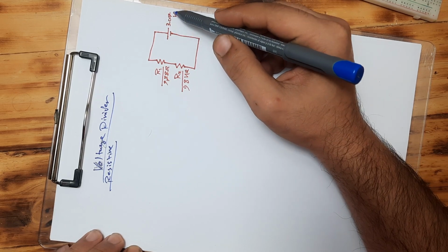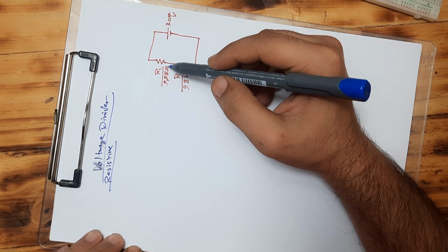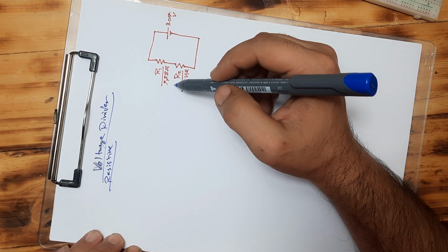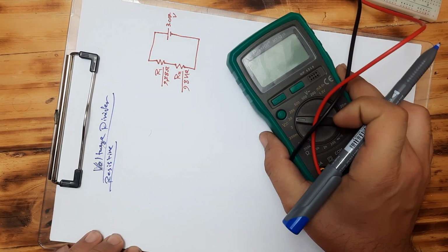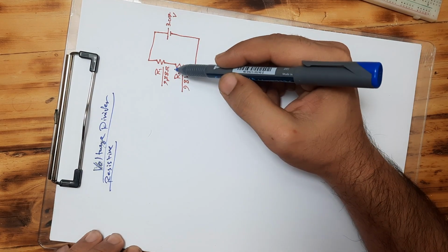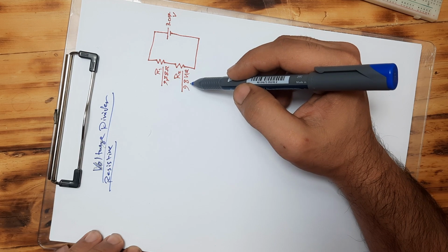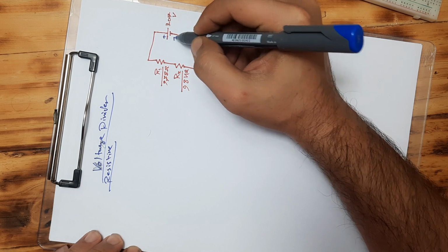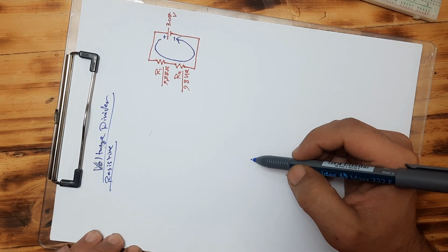Anyway, if we take a look at this circuit here, we can see that we have a 3.07 volts battery. We have two resistors connected in series, R1 and R2. Now these are supposed to be 1K resistors, but I always measure resistor values with a multimeter, because there are always some inaccuracies. As you can see here, R1 is 978 and R2 is 984.